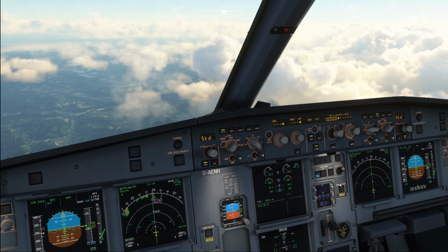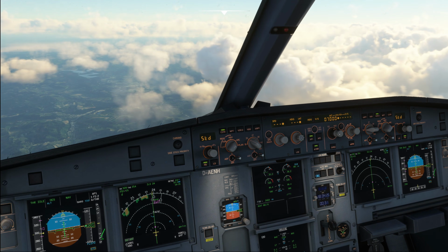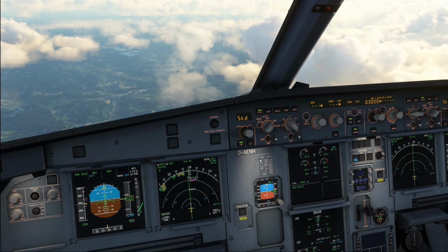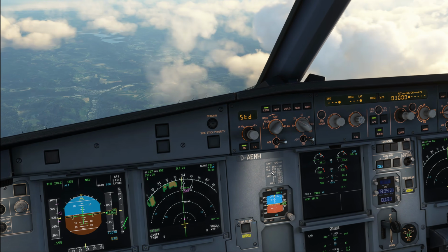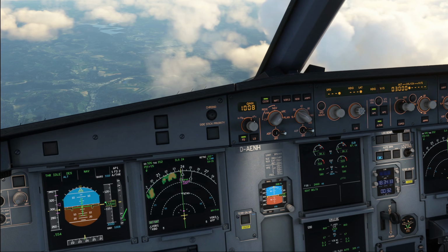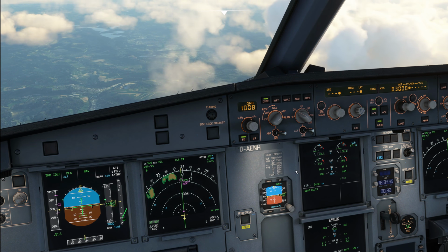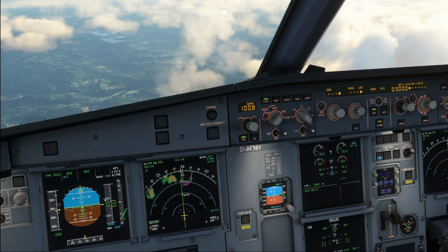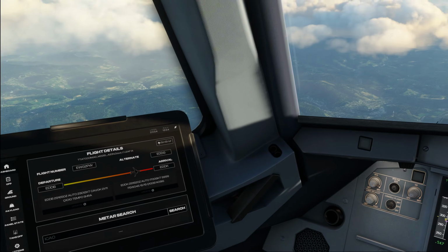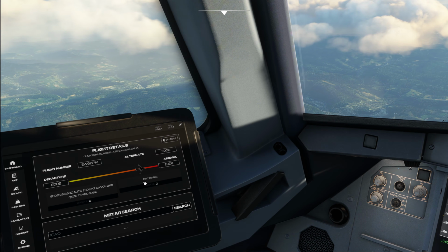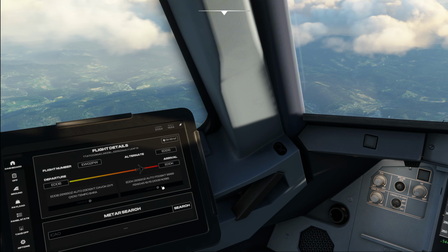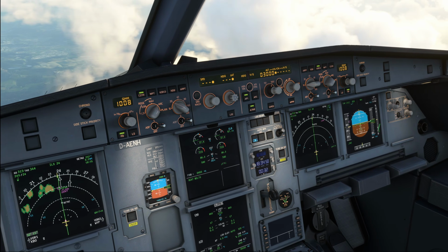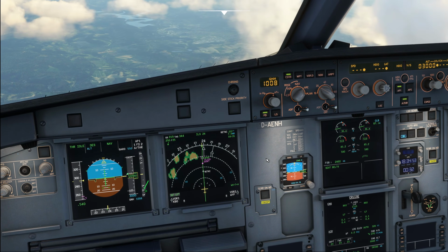Now, at some point, air traffic control will clear you down to an altitude, let's say for example 3,000 feet, and when that happens, you will also be given a QNH. Simply set the local QNH over here. Remember, we also pre-selected it on the descent, so it should automatically already show, but it may be a good idea to run a weather update at this point to be sure that you have the latest possible weather. So in our case, you can see 1008 is the correct QNH. Cross-check that on all three altimeters.